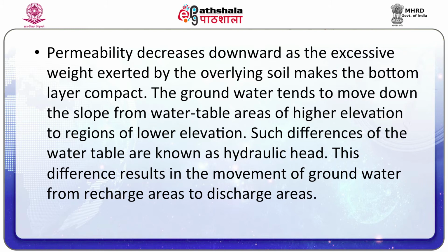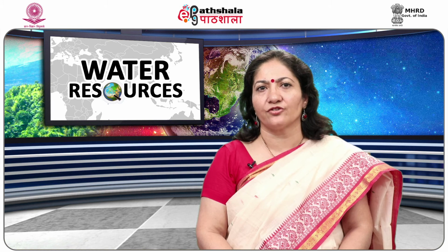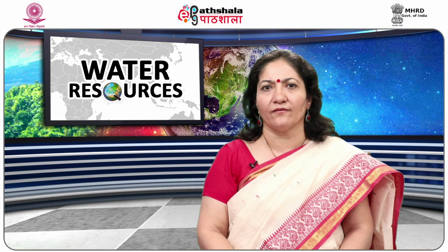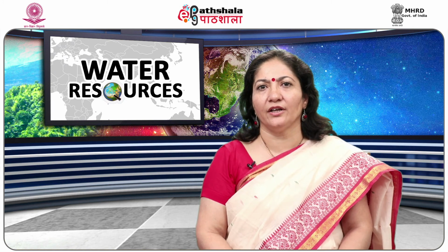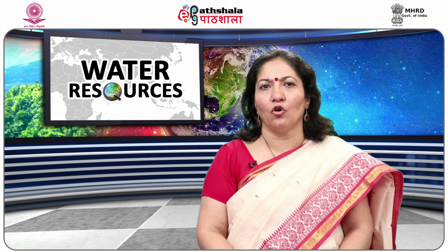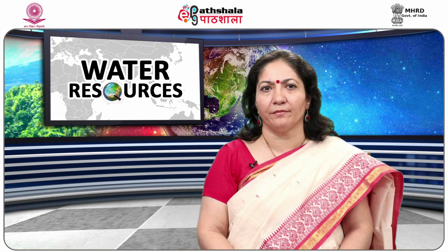The groundwater tends to move down the slope from water table areas of higher elevation to regions of lower elevation. Such differences of the water table are known as hydraulic head. This difference results in the movement of groundwater from recharge areas to discharge areas. Groundwater may naturally come out from the subsurface and flow in the form of a spring, stream, lake, ocean or seep, or by being transpired by plants.